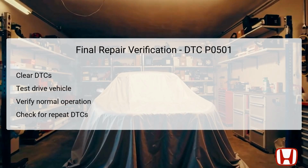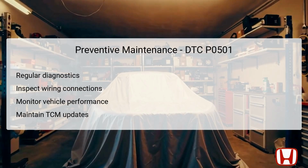TCM. Preventive maintenance is a proactive approach that can help avoid the reoccurrence of issues related to DTC P0501. Regular diagnostic checks can preemptively highlight any discrepancies in the CVT speed sensor or related systems. It's essential to periodically inspect wiring connections to ensure they are secure and free from wear or damage that could lead to faults in communication.